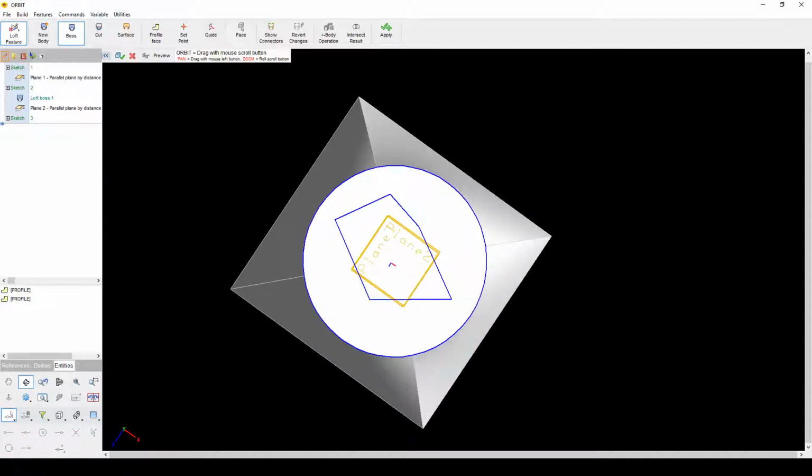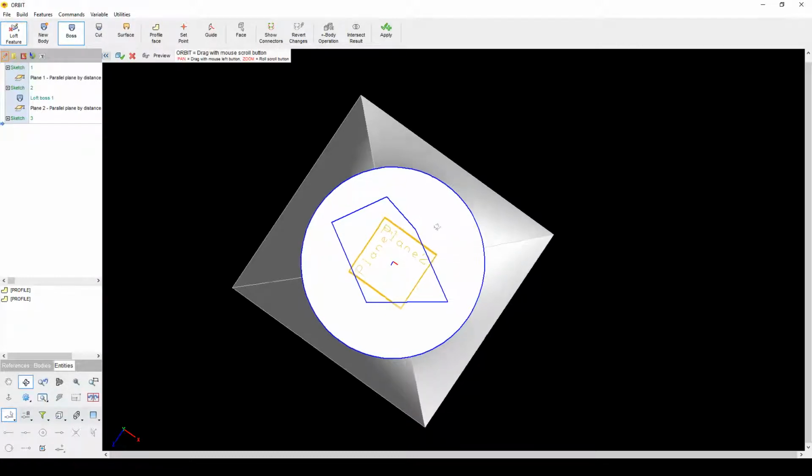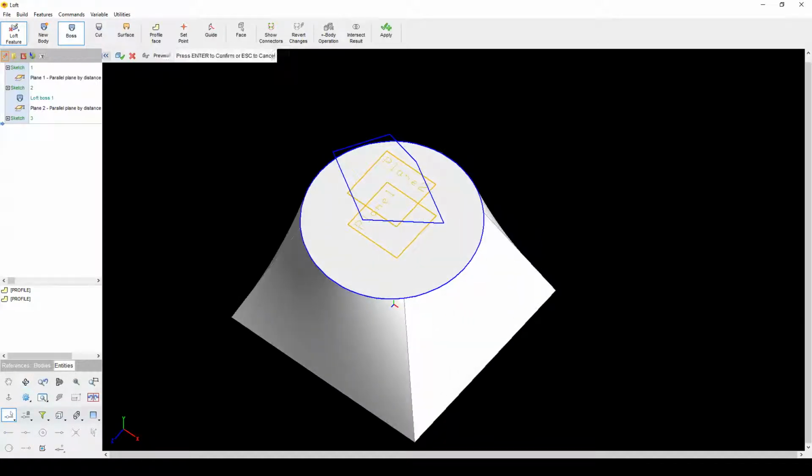You gotta remember, everything in a parametric modeler is defined by math. So trying to loft this circular shape, this perfectly round shape, onto this oblong shape right here is extremely hard. And go back to sketch 3. I'm going to select multiple lines.